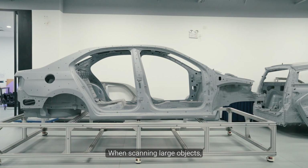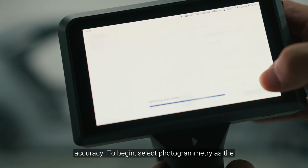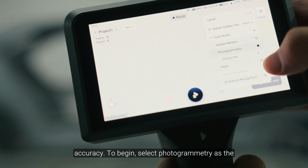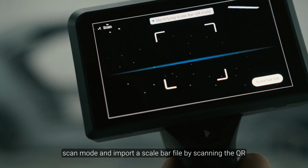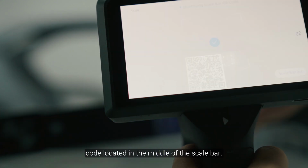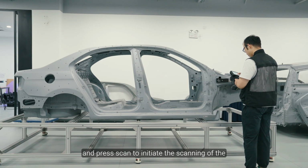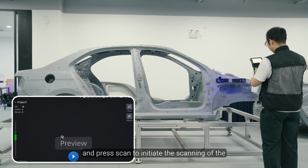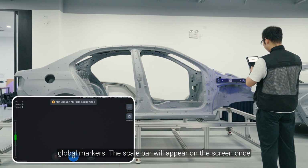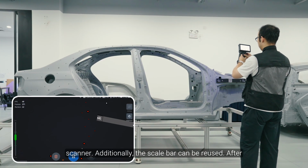When scanning large objects, photogrammetry significantly enhances the volumetric accuracy. To begin, select photogrammetry as the scan mode and import a scale bar file by scanning the QR code located in the middle of the scale bar. Next, place the scale bar around the object and press scan to initiate the scanning of the global markers. The scale bar will appear on the screen once two coded markers are detected by the scanner.